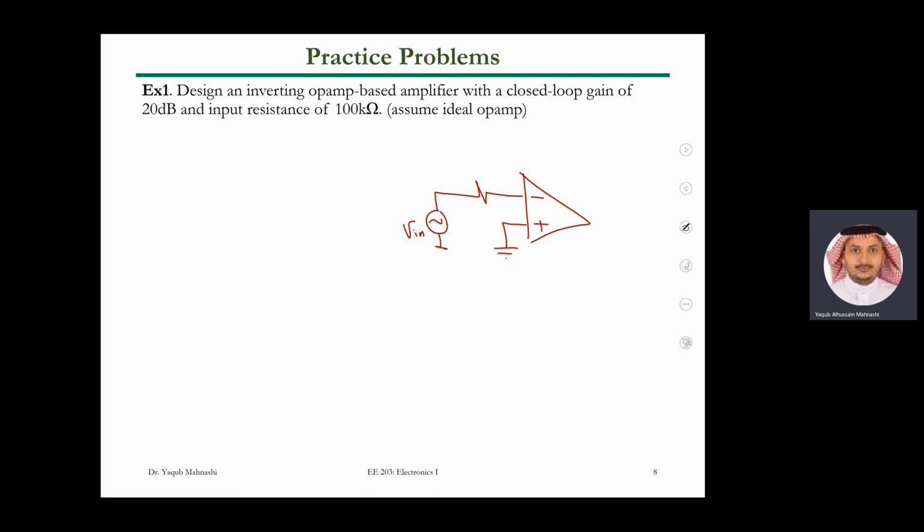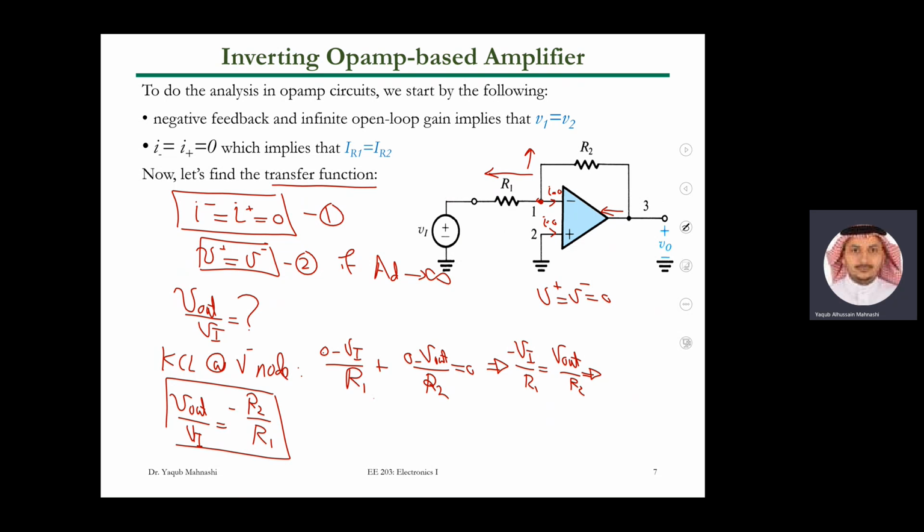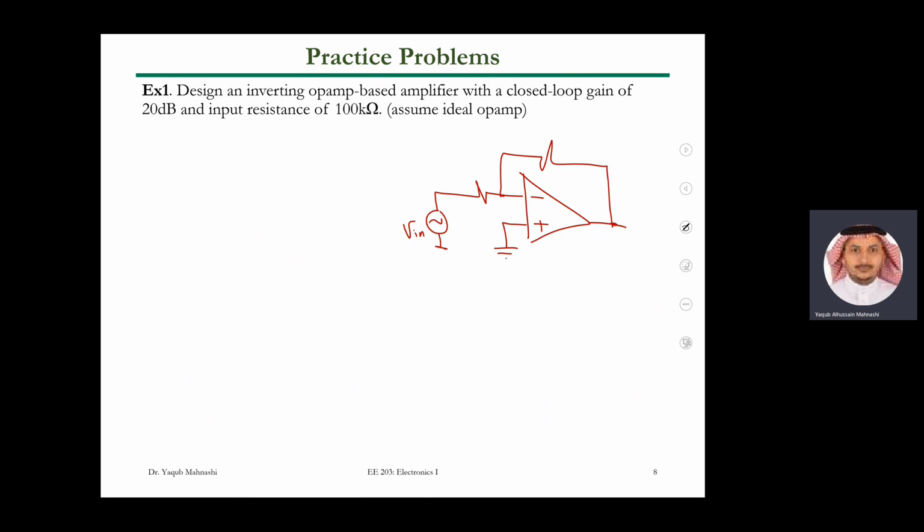And then you have another resistor here, because this is closed loop with negative feedback, right? It is connected to the negative terminal. You can see that also from here; it is very obvious that you have a negative relation. So this is R2 and this is R1. What is the equation we are expecting? The transfer function, V out over V input, equals minus R2 over R1.